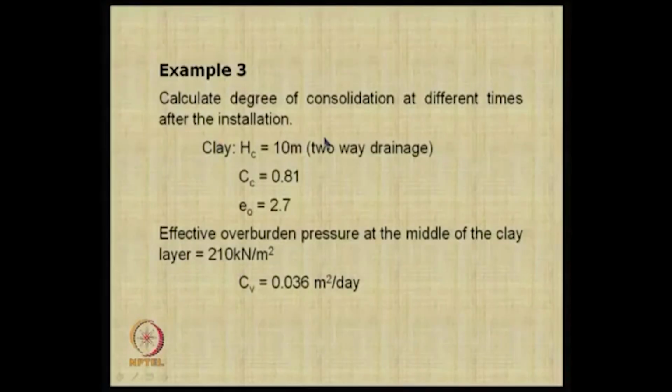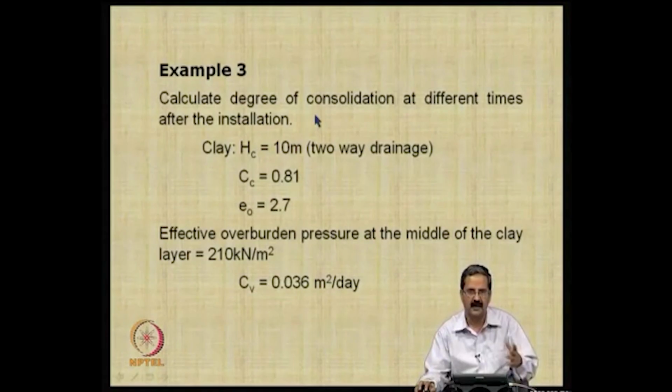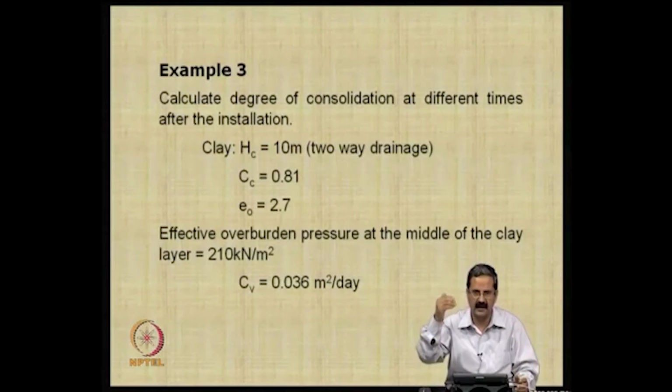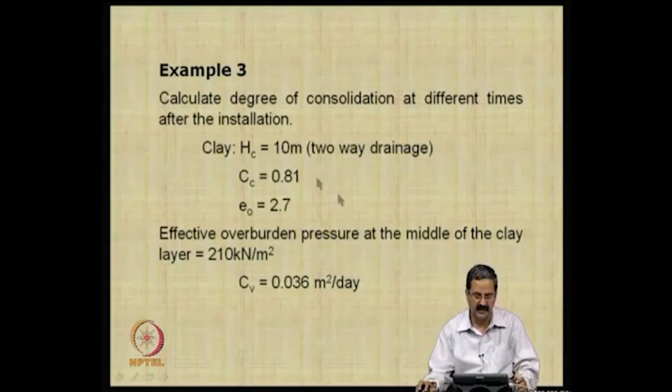Another important point that we have to calculate here is that you should be able to calculate degrees of consolidation at different times after installation, because we know that this consolidation can be very low, and then we would like to increase it using sand drains or prefabricated vertical drains. For the same example, I will just give a similar typical example.